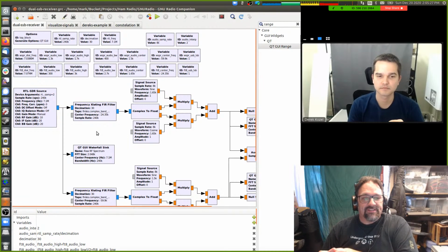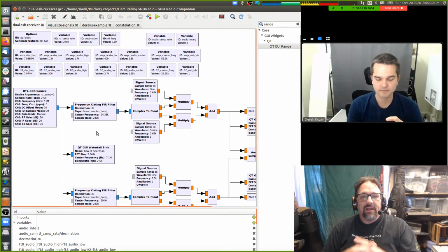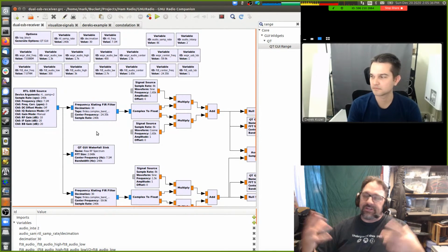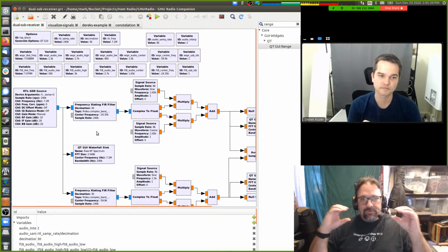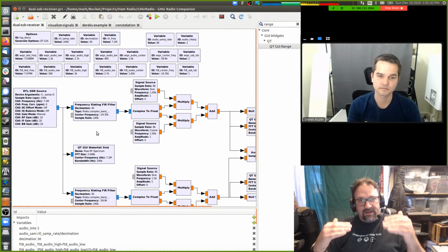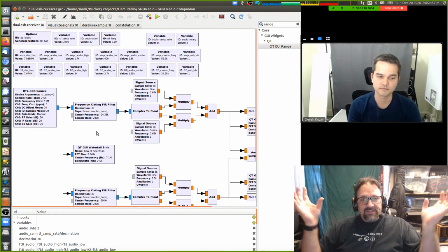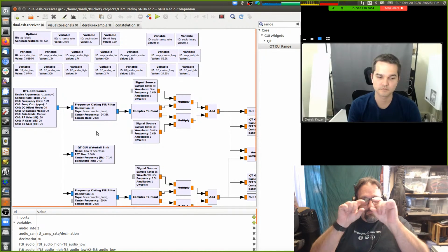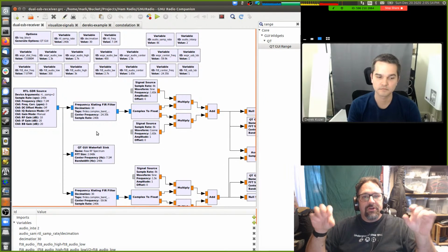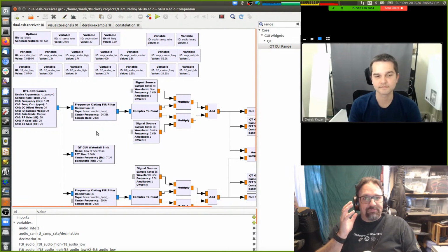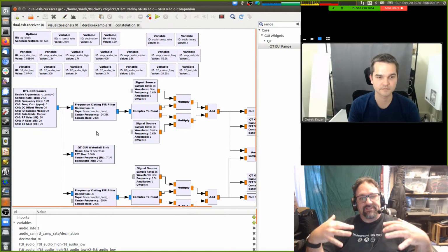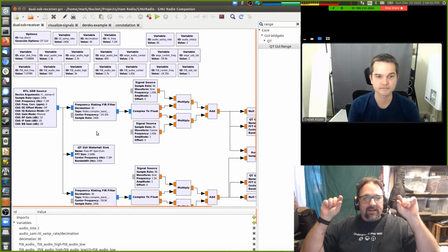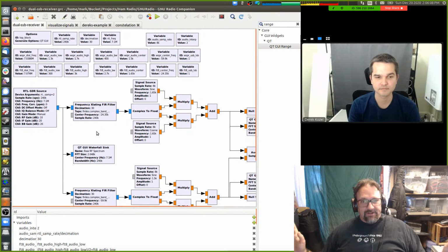If you choose those constants correctly, you can get this shift register multiply-sum output thing to do so many rad things. A simple example, like what we're using it here for, is as a low pass filter, or you could use it as a band pass filter, or a high pass filter or a notch filter. All these different things you can accomplish just by multiplying these constants by the values in the shift register, summing them together, and outputting that. By intelligently picking what those constants are, you can do some magic stuff. And so that's what a FIR filter is. Just that mechanism of multiply these constants, sum, and that's your output. And then the magic comes in selecting those constants. Do not ask me how to select those constants.